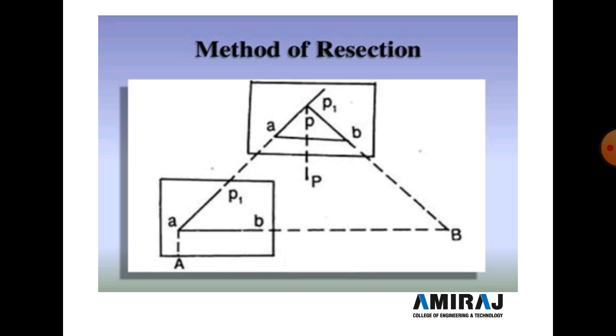Now the table is shifted and centered in such a way that p1 is just over P. So all the setup is transferred to point P, and approximately the point p1 on paper is just over the point P. Orientation is done by backsighting the ranging rod at A, and with the alidade touching the point b, the ranging rod B is bisected and the ray is drawn. Suppose this ray intersects the previous ray at point p.